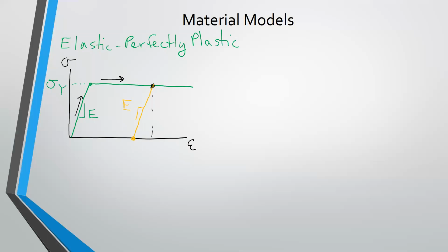So we have zero load in this member, but yet we have a non-zero strain. That means that after we've completely unloaded this, where we take the specimen off the machine, it still has some amount of strain in it. So this portion that is underneath that unloading triangle is the recoverable strain.